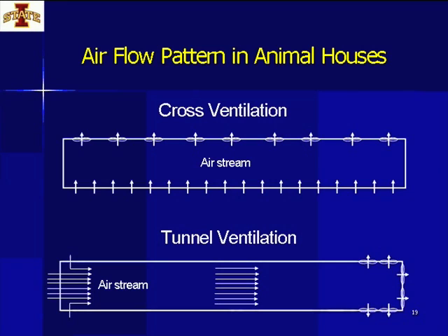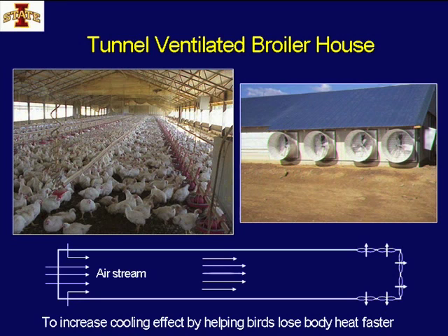Just a review of the airflow pattern in an animal house. Kevin already touched on this: cross ventilation and tunnel ventilation. And here is an application of tunnel ventilation in a broiler barn. The idea is basically to increase the cooling effect by helping birds lose body heat faster.